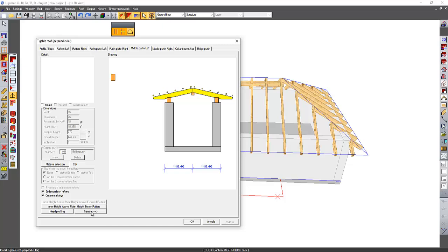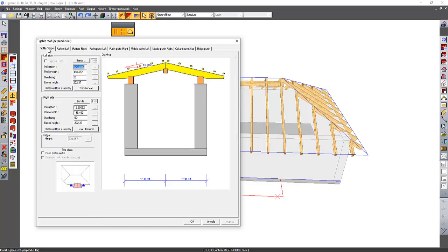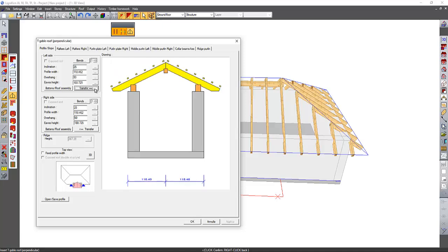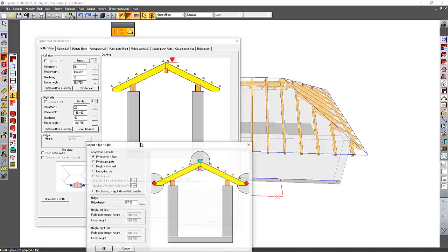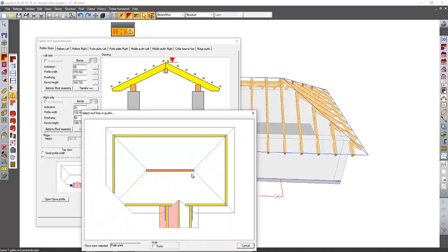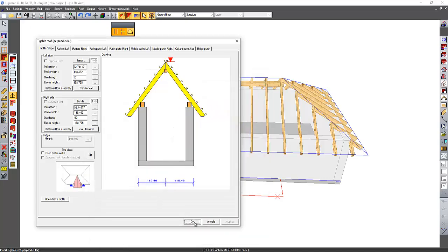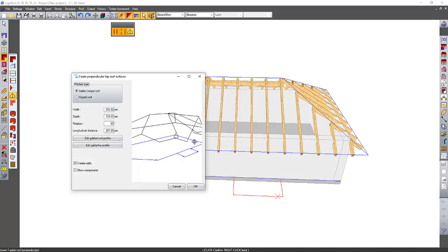We don't need it, or you change the property, I don't want to do it. Here we say 25, copy. I can also click this and I can say to the pivot, the rotation is on the eave, and I will arrive here on the ridge. I confirm.